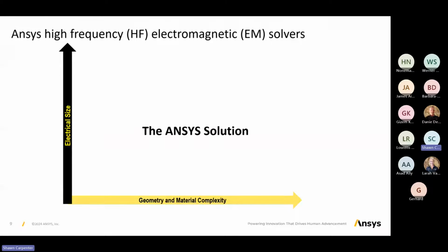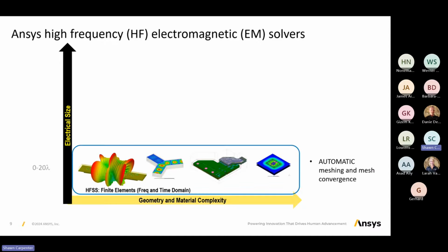So I mentioned earlier that it takes a number of solvers. The set is not too large, but it does take a family of solvers to accomplish all of this. When we're working with things at very high detail, like antenna designs, board designs, chip designs, these usually have very complex arrangements of geometries and can have very exotic materials. There may be ferromagnetic materials, materials with tensor permittivities or tensor permeabilities that are different in each of the three dimensions and depend on the space in which they're located.